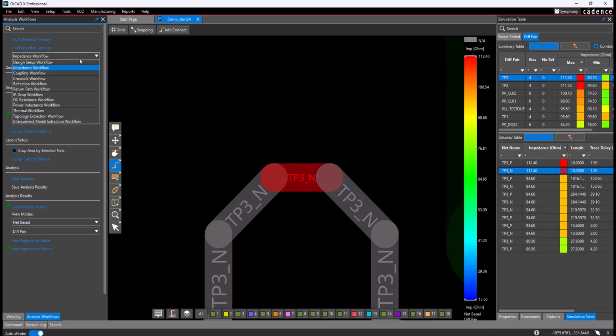You can then use another workflow like crosstalk, reflection. They can start sending impulses down these transmission lines, and then you can measure it. So you have a lot of different types of analysis at your disposal. Some people just use rule of thumb, saying, I'm just going to reroute this differential pair and slide around and find and fix it that way.